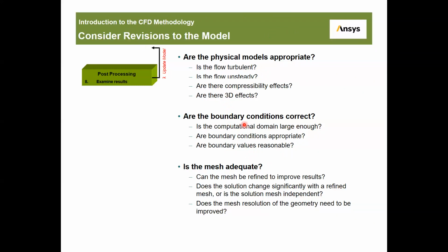Okay, if you use 1000 mesh, you get one value, for example pressure drop, let's say 10, and then you make 2000 meshing and you get 15. So we call that your result is not correct. It depends on meshing. We don't want that. We want our result to be independent of meshing.